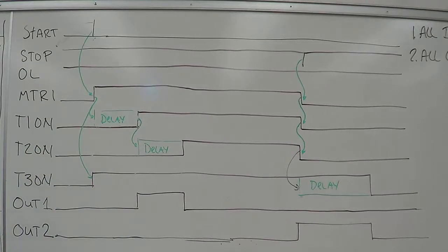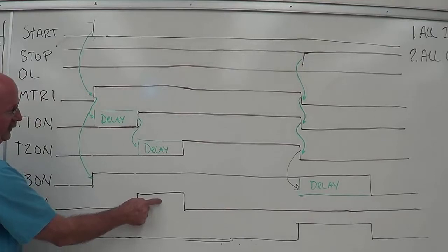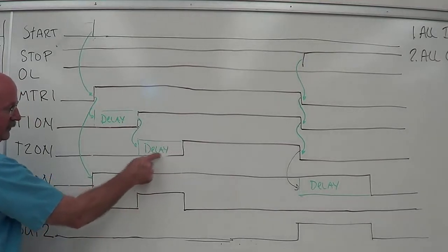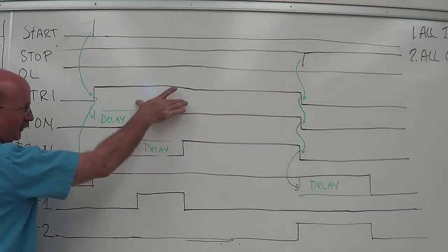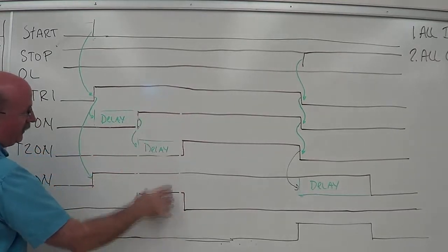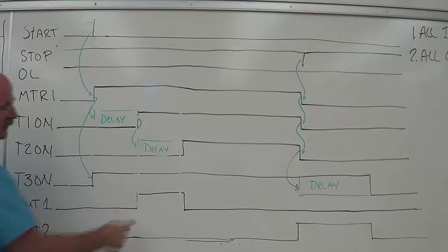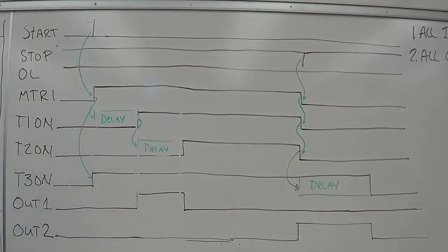So drawing the timing diagram, you can draw all that out and you say, okay, now I can see how it operates, but how do you implement that in the PLC code? If we look at this output here, this is on when this delay output here is off, and this output here is on. So if you come straight down there, you see that's on, that's off, so that should be on. You guys follow me on that?